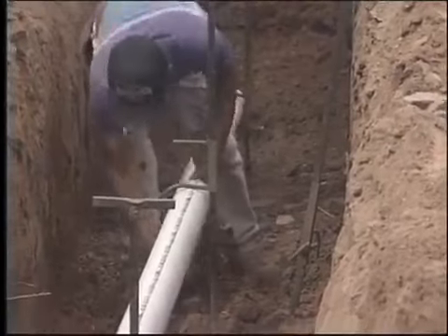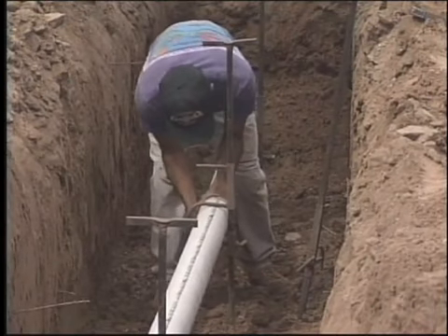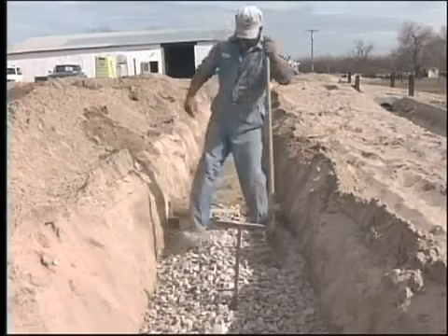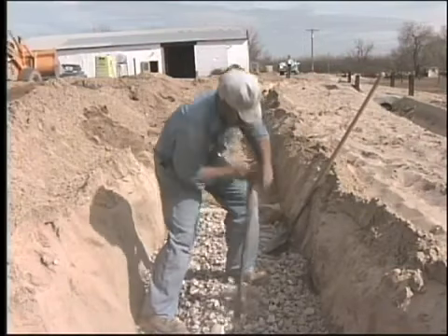These steps of placing the bottom gravel and placing and leveling the pipe can be combined into a single operation by placing the pipe on standoffs or chairs, which hold the pipe at the desired elevation. The gravel is then simply dumped in and smoothed off.